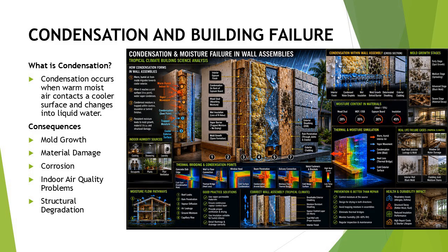Moisture accumulation creates ideal conditions for mold growth. Mold not only damages materials, but also affects human health. Architects must therefore understand dew point behavior, humidity movement, and temperature differentials. Failure to address condensation can compromise the entire building envelope. A beautiful building that cannot manage condensation will eventually experience performance failures.